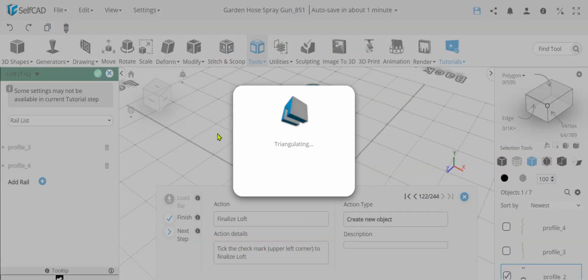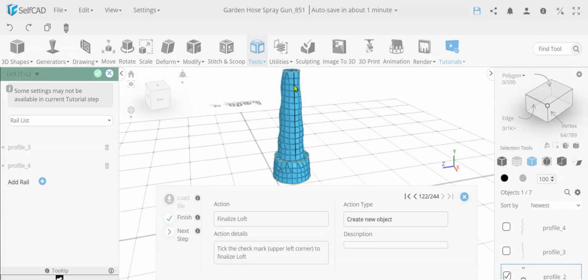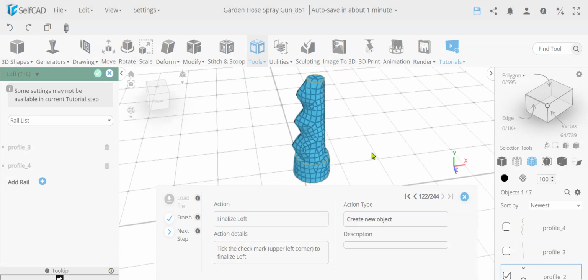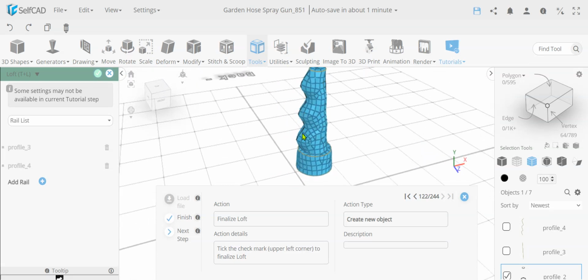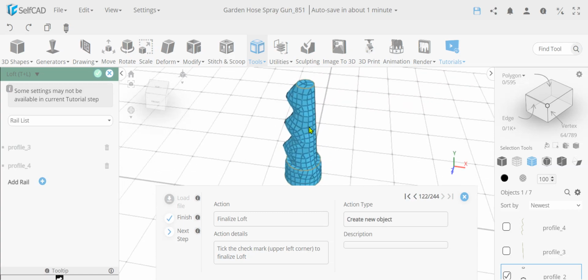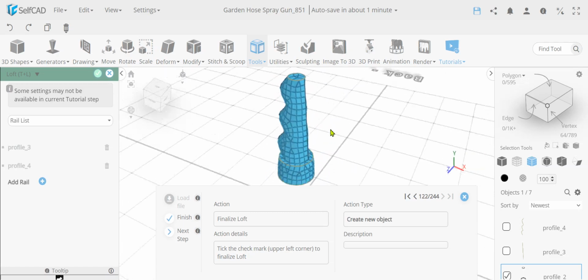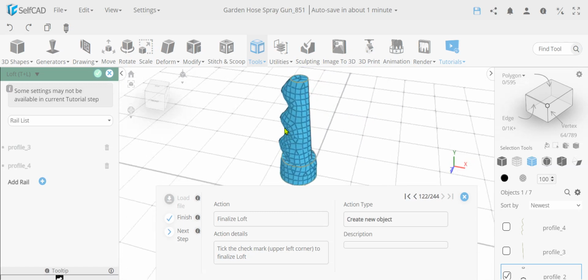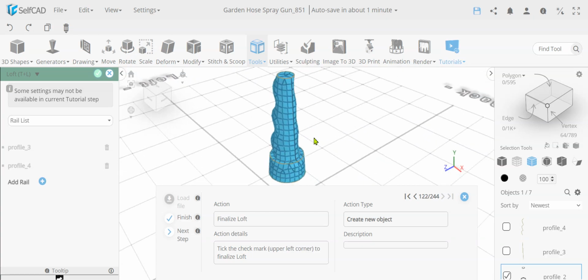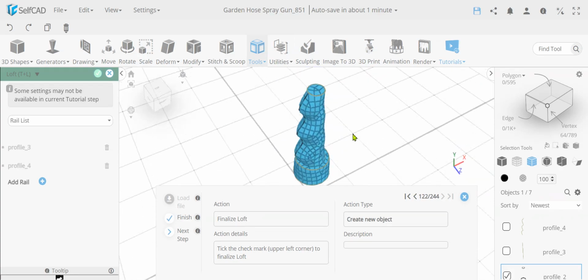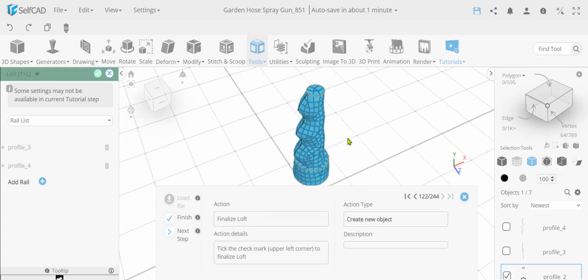Okay, so why did we have to add this rail over here? If I added this first, you could have visualized it, but now that we added this first, I can visualize it, so I have to explain it. If we add this rail, it's basically going to bend the entire shape, and it will bend the back also. It will kind of offset the entire shape. So after adding this, we need to add the back one as well to make it a stopper, to say, okay, here is where the rail stops, and that's basically the way rails work. You can add multiple profiles and make them work.